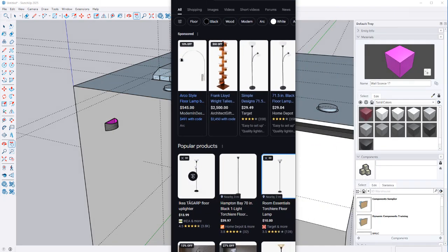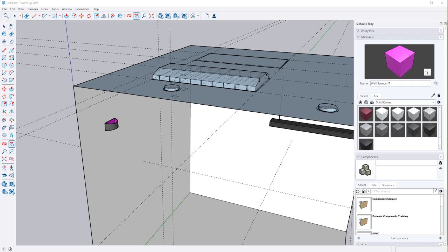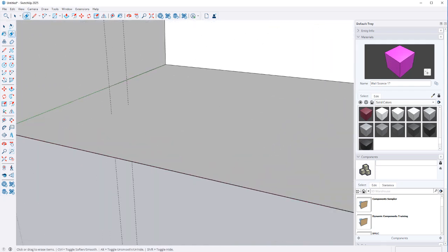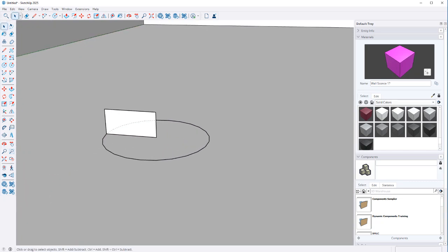So we've got the ultra generic, ultra classic, just kind of stand pole and a bowl kind of light on the top. So let's do one of those because they're pretty easy to do. I've shown you guys before how to do that profile cutting. So what we'll do is we'll just make this right here 2 inches thick. We'll give it a 5-inch radius, 4-inch radius. So we'll make this profile right here, and then we'll draw a circle on that, and then we'll use this profile right here.